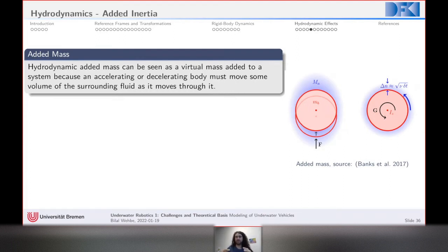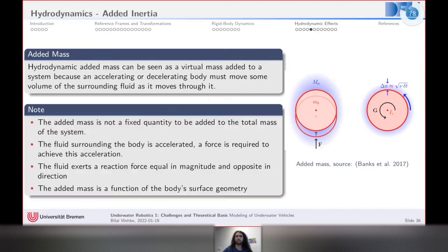What happens is that all of the layers of the fluid or water that are very close to the body are going to be accelerated way faster, so there will be a higher force, and this force will diffuse the further away you move from the body until it reaches zero, basically. And this is only due to the shear forces or the viscous forces, assuming that the fluid is composed of layers, and there are shear forces between those different layers.